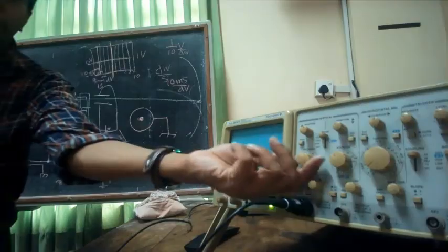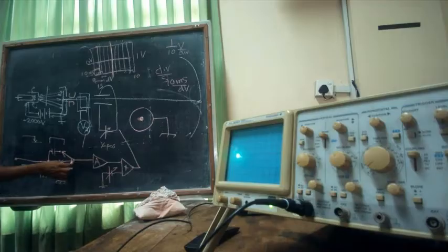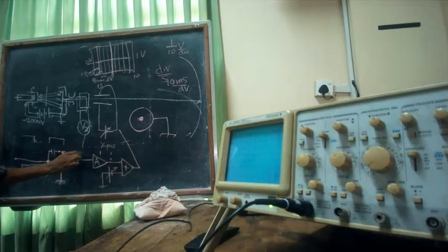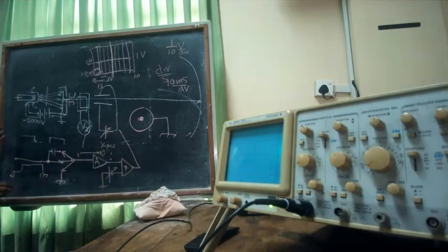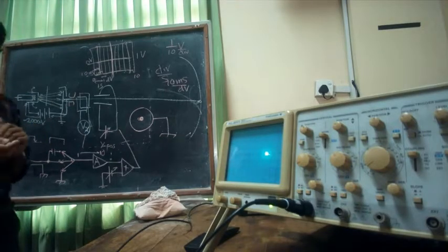The gain of it is controlled by this. Once you change the gain, now I said output can be only between 0 and 1, right? What maps to that 0 and 1? Let's say if I have a gain of 1, then 1 volt maps to 1 volt. But if this gain inside is 10, when the voltage is 100 millivolts, output will be 1. Correct? Output will be 1 when the input is just 100 millivolts. Right?